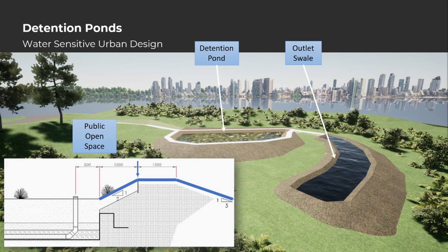So we've got the arrow here showing where we have our center line. We'll move to the left with a distance of 1 meter at a slope of 1:2, and we'll call that code where we hit the bottom of our pond, the bed of the pond, and then the bank will be the top of our bank on the right, and I refer to batter as where we slope down to existing ground. I think in the US this is called daylighting.